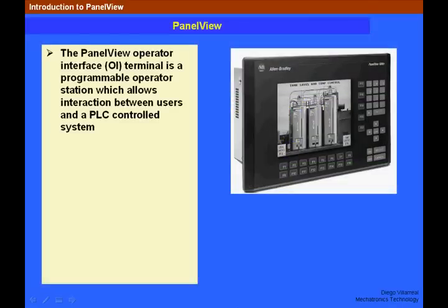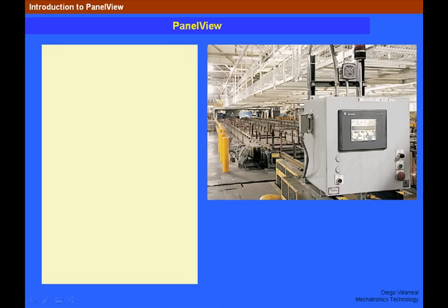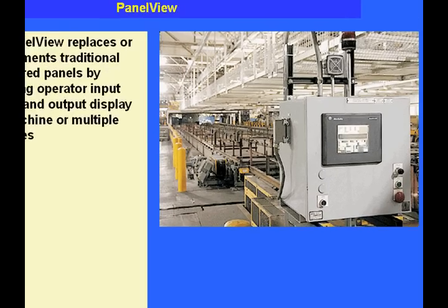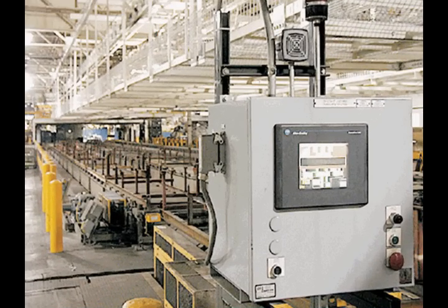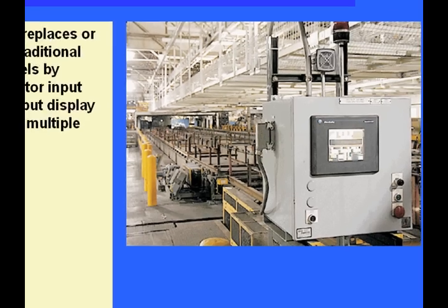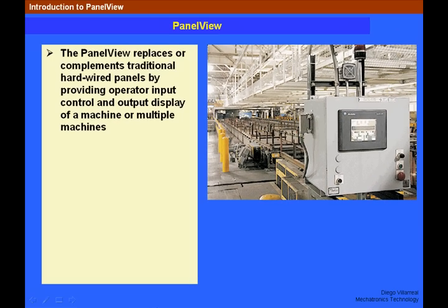The PanelView operator interface terminal is a programmable operator station which allows interaction between users and a PLC controlled system. The PanelView replaces or complements traditional hardwired panels by providing operator input control and output display of a machine or multiple machines.